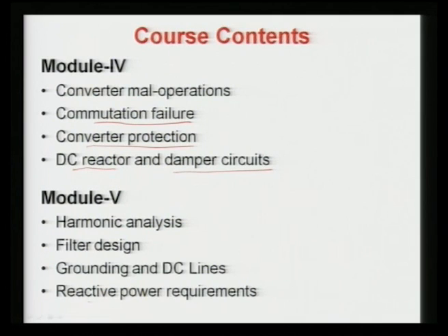Another aspect of this module is that it will also analyze the reactive power requirements. If the filter circuit is designed for particular harmonics to provide the minimum impedance for those harmonics, this filter circuit also provides reactive power support to the converters for the fundamental components, and that will be analyzed, and we will see the requirement of reactive power.